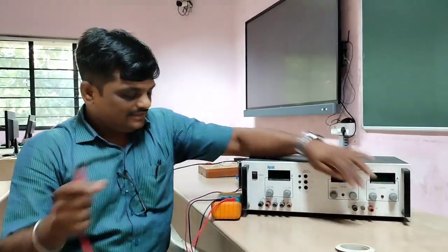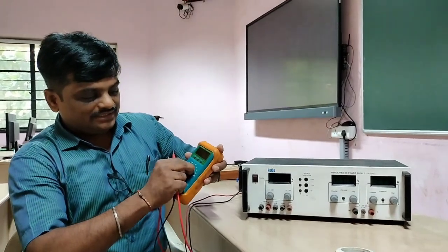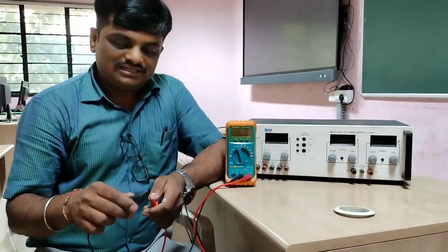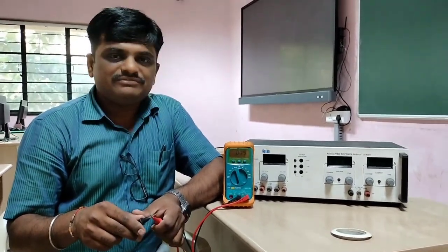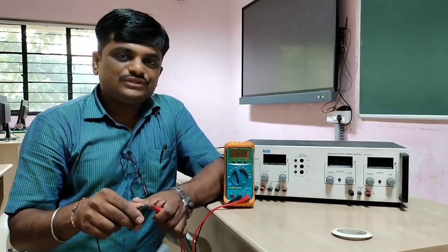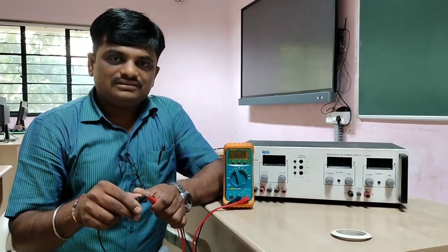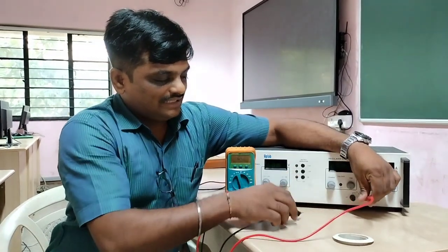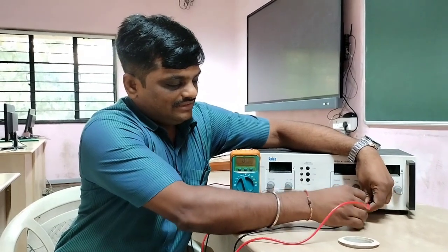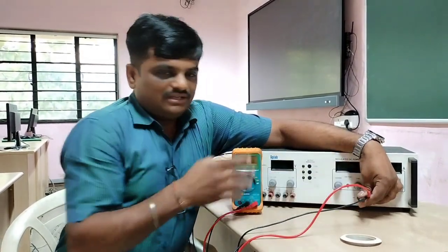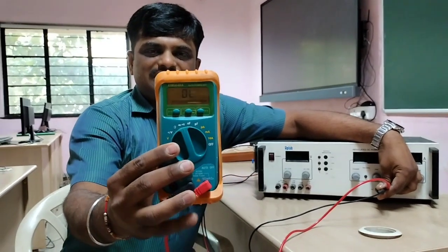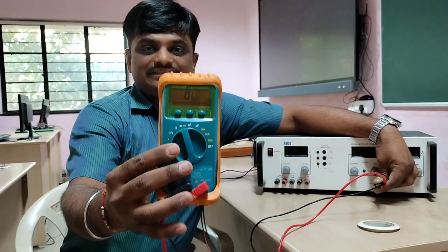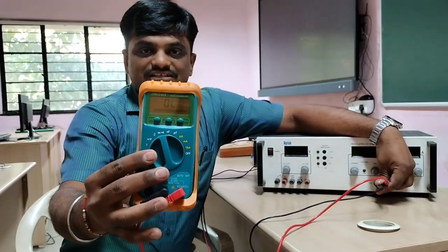If they are not shorted, it indicates that they are not connected to earthing or ground, hence they are floating in the air. So I am putting this multimeter on continuity mode. On continuity mode, the multimeter will give a sound when the resistance is negligible, so that is why it is showing continuity. You can hear the sound, right? Now I am putting one terminal of this multimeter on the earthing terminal and the second terminal on the neutral. We can see that the multimeter is not giving any sound, rather it is showing that the resistance is very high, over limit. That indicates that the negative terminal is not connected to ground.